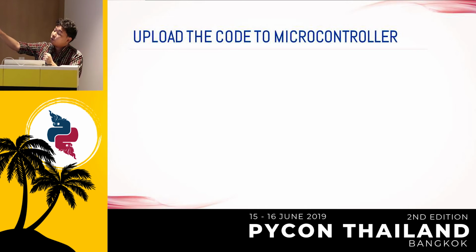So we have the IC driver here. The IC driver is actually driving the solenoid valve in the first version. In our first version, we were not using the ER fluid, and it is a problem here. We are going to talk about it in the last topic. It had a problem with heat. It heated up because the electromagnet heats up when you instantly energize the coils.